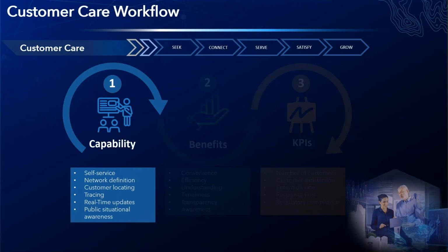What we've seen in this customer care segment also highlights tracing. Answering many questions requires that you be able to determine a path directionally based on connectivity or traversability from a specified starting point in your network to a barrier or barriers that bound it. The utility network provides powerful tracing capability through 8 out-of-the-box options, as Matt discussed earlier. We've also seen a glimpse of the role subnetworks play, subnetworks being topological sections of a domain network, like isolation zones in this section's gas utility example.